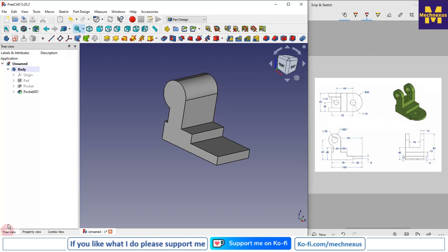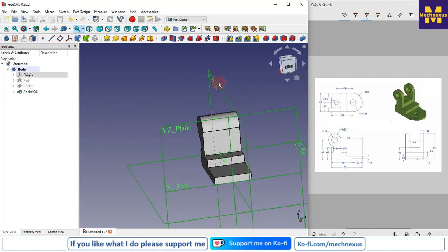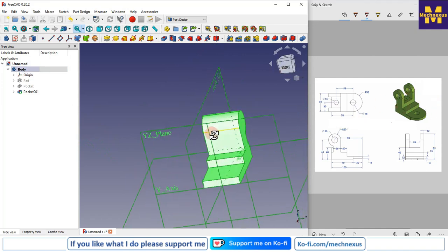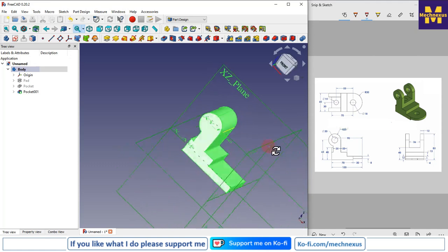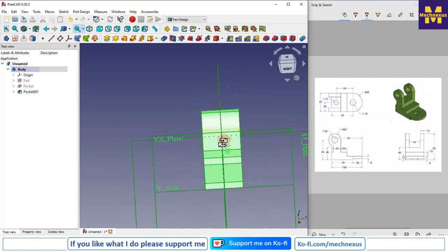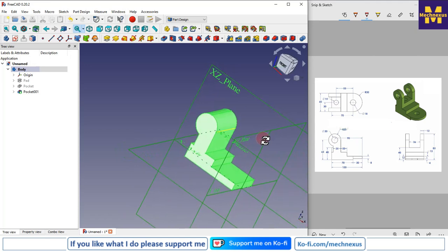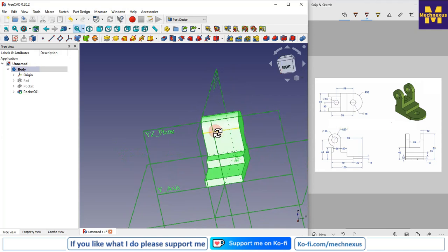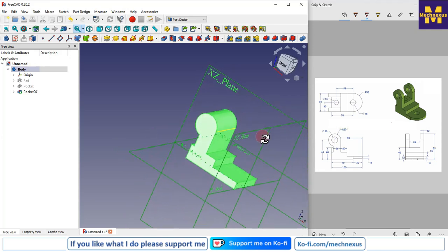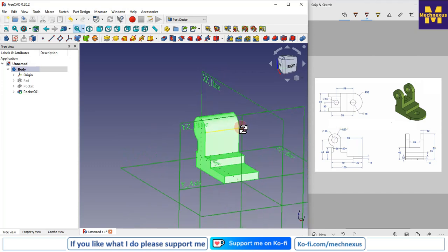So for this we will select our mid plane. That's why I have made the extrusion symmetric, so that I get a plane in between of my part. This is a very good practice to imagine the model in your mind before making the drafting, because once you select the wrong face or wrong feature and you have not taken the proper datum plane for your part, it will increase the modeling time.